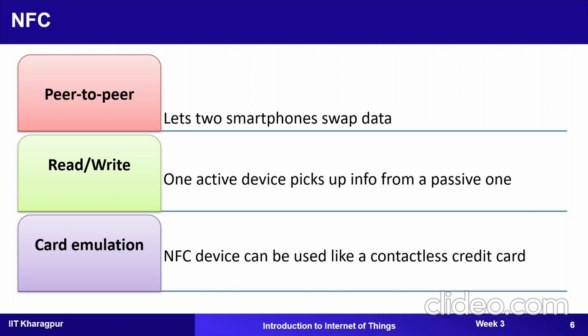The devices can communicate with each other whenever they are in range, and when devices are not in range, the packets or messages are routed with the help of hopping, bypassing the obstruction, or with the help of the nodes present in between. The process of bypassing the radio dead spots is done using a message called healing. And as Z-Wave uses a source routed static network, mobile devices are excluded from the network and only static devices are considered.